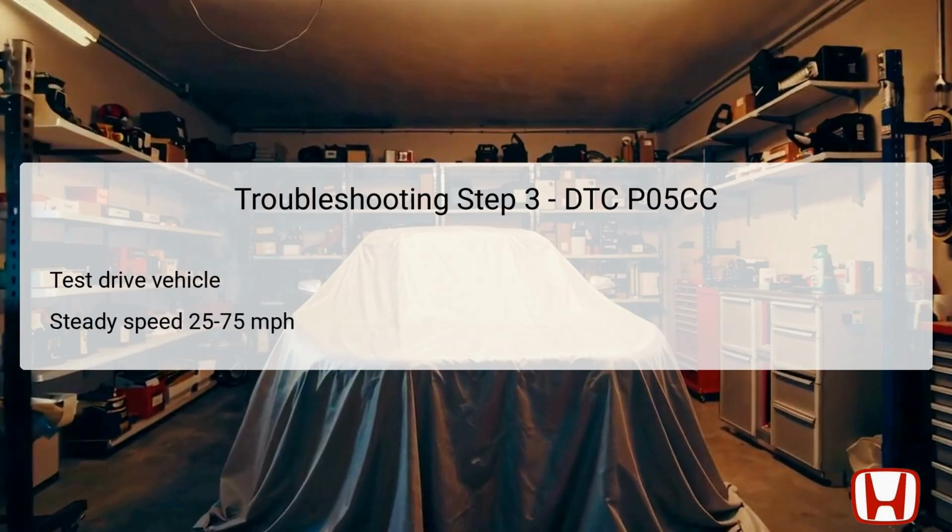The next step involves conducting a test drive of the vehicle at a steady speed between 25 and 75 miles per hour, 40 to 120 kilometers per hour, for a duration of 10 seconds or more. This real-world test enables observation of how the VTC system behaves under driving conditions.